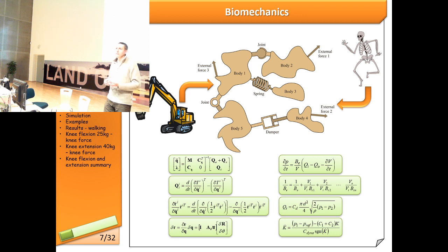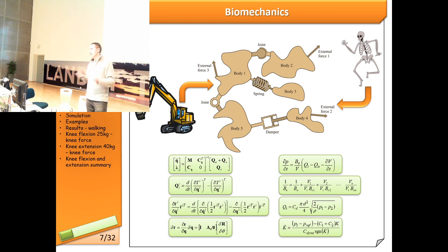That's how it's modeled in mathematics. But on our higher level, we represent them as joints which restrain some degrees of freedom. In between, we can have some spring elements and damper elements, both modeling a machine where you have some compliance, and it can be modeled as a spring and damper system.